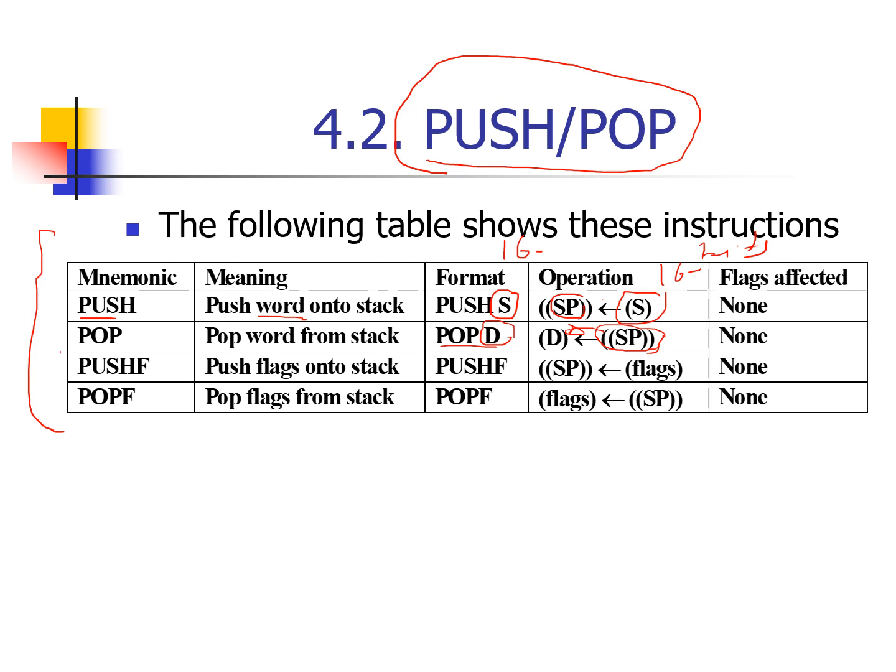And you do the same with the flag register. You push F, which takes the flags from your flag register and stores them into the stack, again in a place pointed to by SP. You bring back your flag bits from the stack by pop F. So now you get it back to flags. Good.